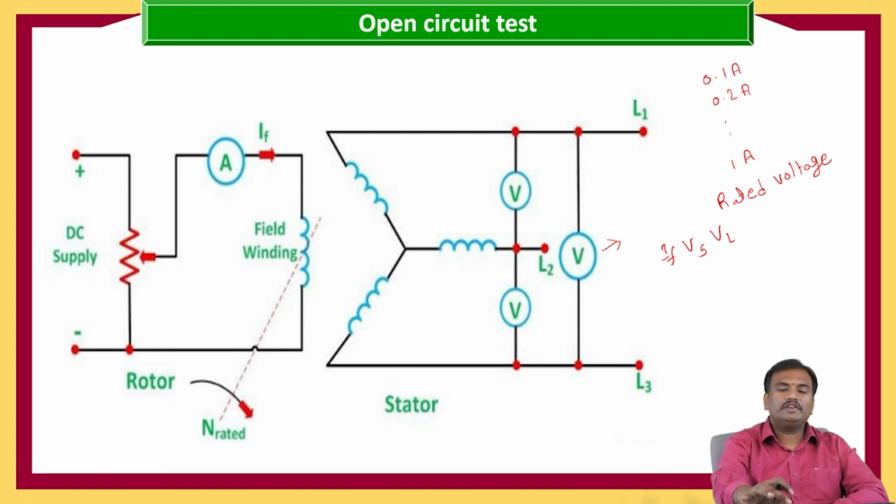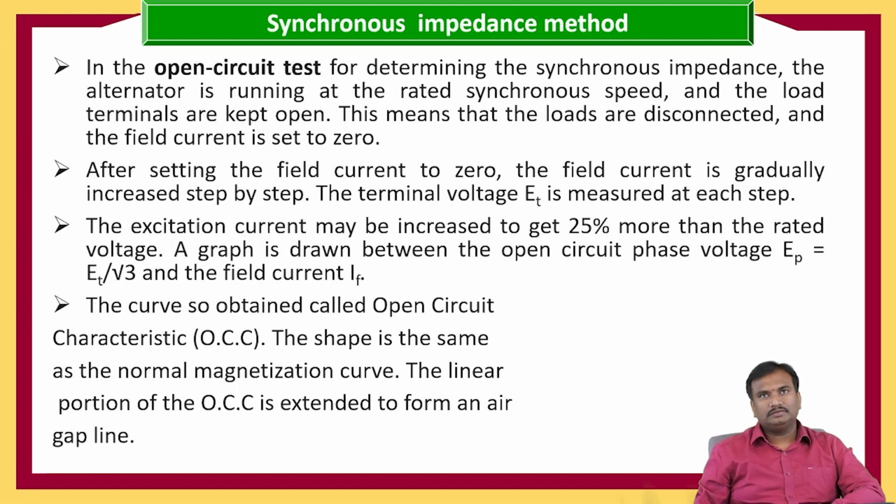Here the generator side is open circuited, no load is connected, so we can also call it the no load test. In the open circuit test, for determining synchronous impedance, the alternator is running at synchronous speed.